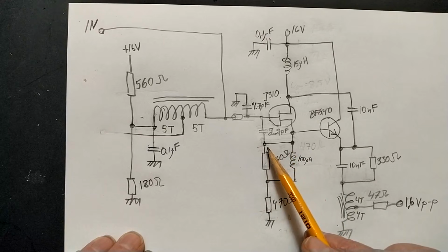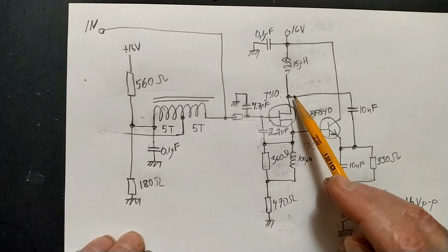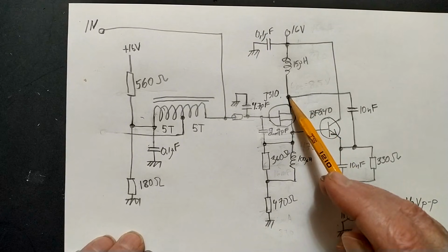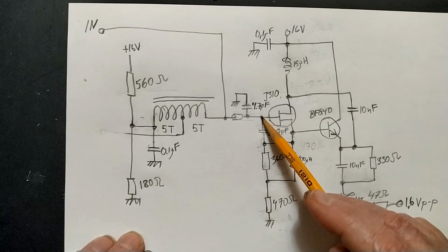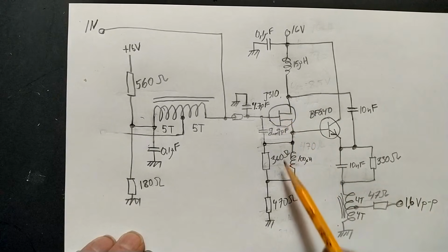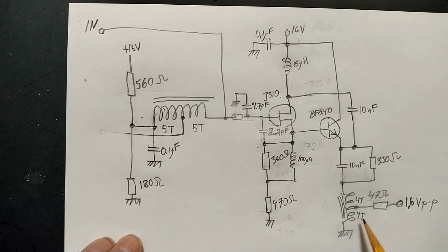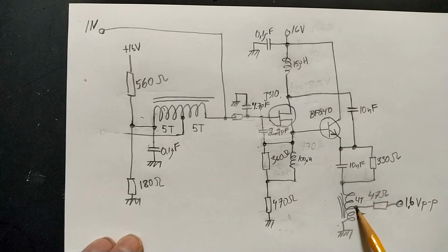It gives a load resistively on the source that makes the AC voltage on the drain just a little bit smaller than on the gate, but it's still pretty close, so this removal of the drain capacitor is almost perfect still. The output impedance of the bipolar is low and transformed to half the voltage. 4 times lower impedance is extremely low. So the output impedance is 47 ohms here.